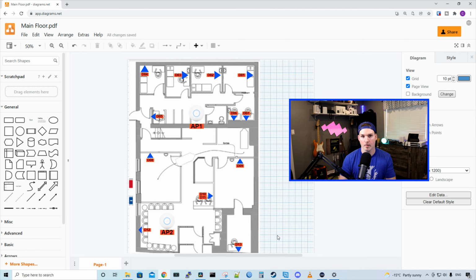When I'm setting up my boxes of cables, I will mark on the cable with a Sharpie the cables that I'll be pulling. So D01, 2, 3, 4, 5, 6, up to 10, or however many cable pulls I'm doing. Once the cable pulls are in place and we're ready to do our terminations, we bundle them into the rack and then we find our D1, D2, D3 and go in order and punch them down on the patch panel.